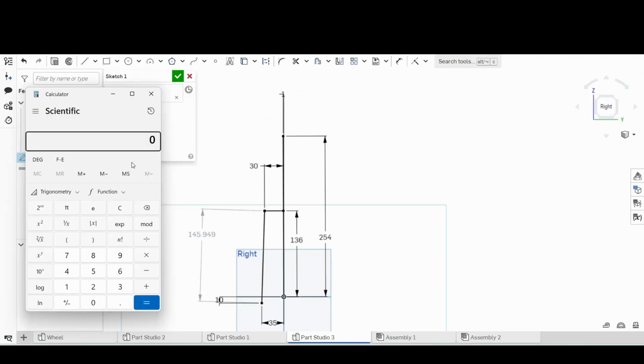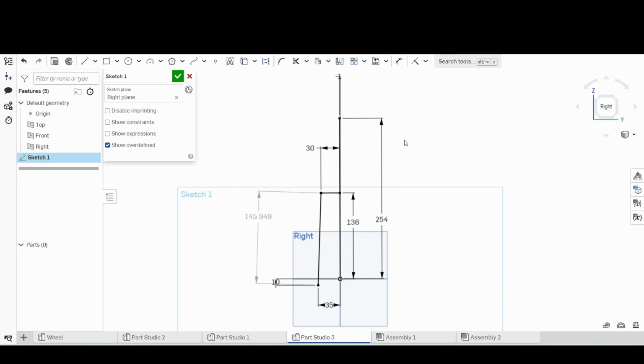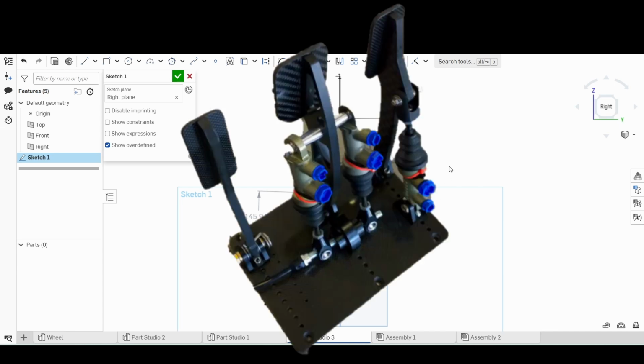So you can find the pedal ratio mathematically doing geometry for your setup. So we can do it in CAD as well. So in this sketch, what we have is the brake pedal with the mount for the master cylinder, and this line's the master cylinder itself with the pivots here and here. So it's just a rough drawing of a setup for the master cylinder and brake pedal.